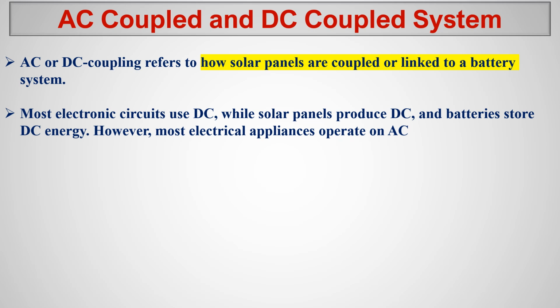Because in the DC coupling system, we send the power to the battery, and then from the battery we take it to the inverter. So there's a loss, because obviously if we charge and discharge, there's a loss. So the question is reasonable. You're asking why we are unnecessarily charging and discharging. Those questions will be answered in this lesson. So let's go to the slides.